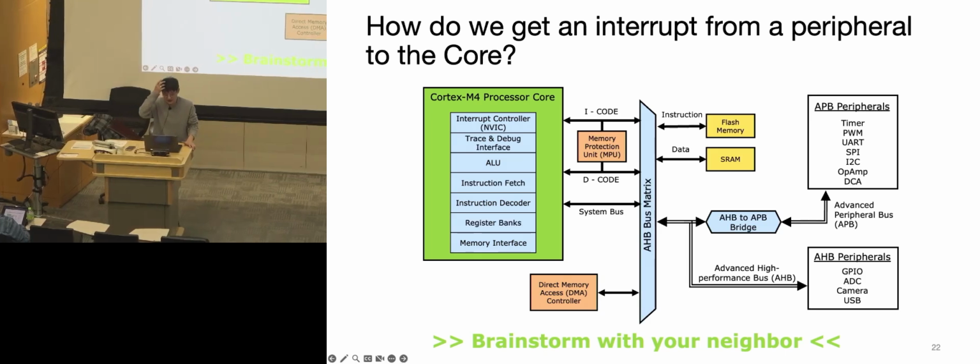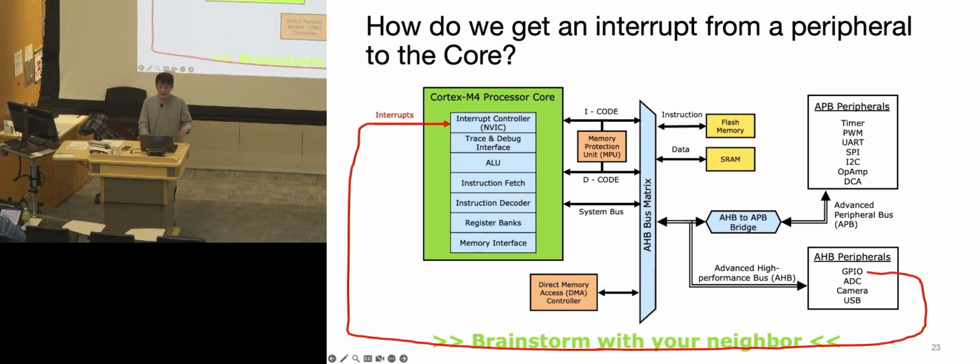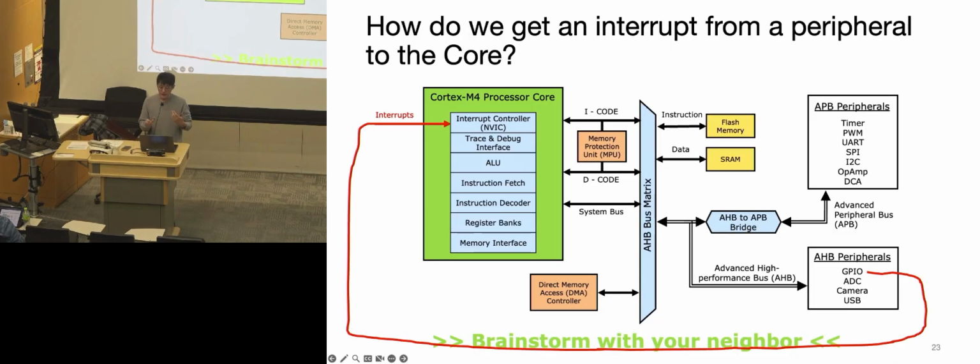Yeah, I think this question is kind of getting ahead of time. So the short answer is we don't typically use buses for that. This is mainly for the latency and prioritization issues, because buses are designed for general purpose data transfer. There's always constantly stuff flowing around on the buses. So if we also put interrupts inside of the bus, which should have a higher priority, then it causes longer delay times.